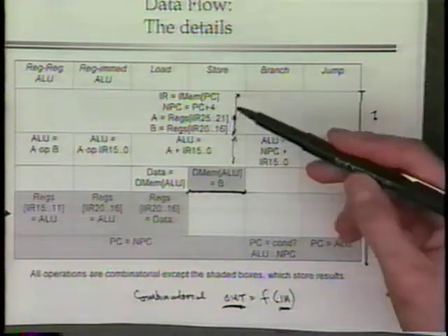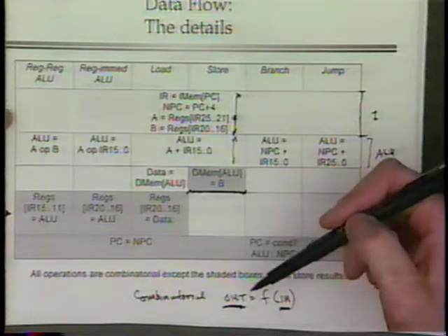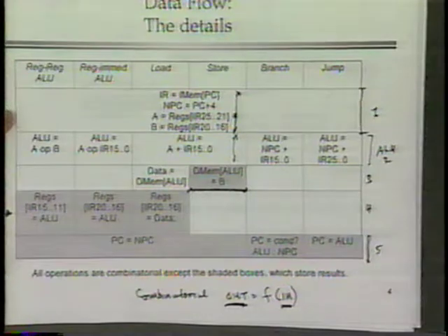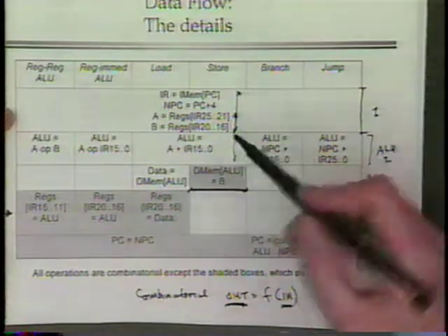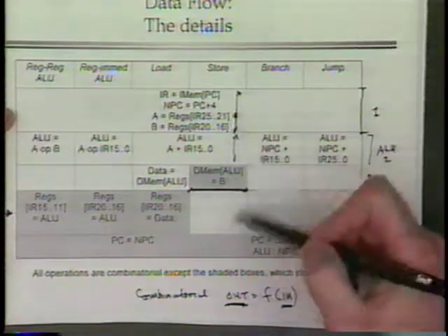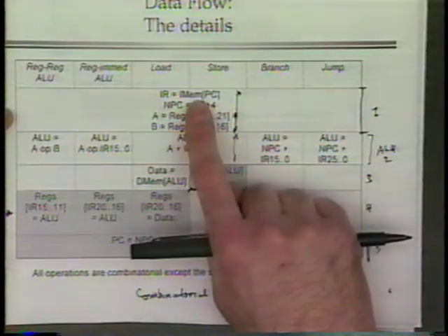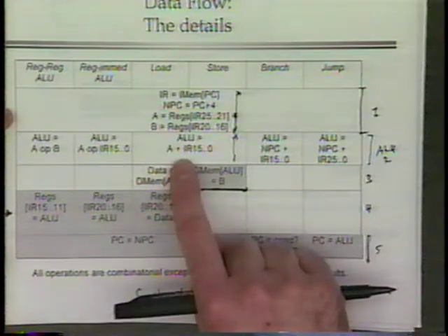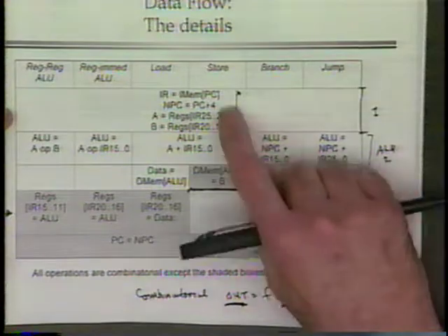In order to make this kind of decision about what things ought to be in what pipeline stages, you've got to know approximately how long things are going to take. And in fact, you'll see different variations of pipelines for the same architecture that move things from one pipeline stage to another as the implementation used for the functional units in any stage changes. If you can somehow figure out a way to make this memory and the register memory blazingly fast compared to an ALU, then it might make sense to put all this stuff in one stage. But in fact, they're not.